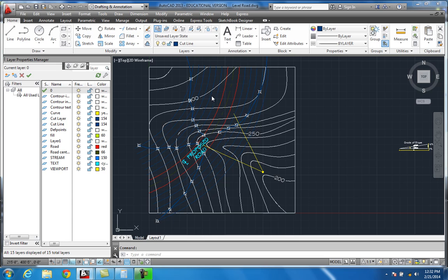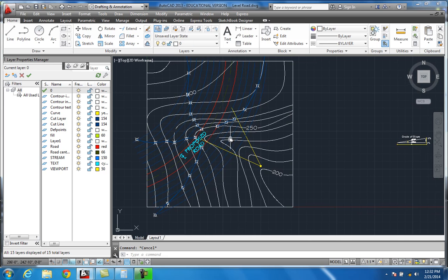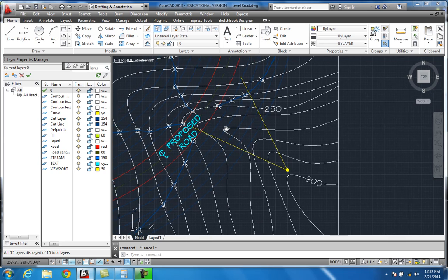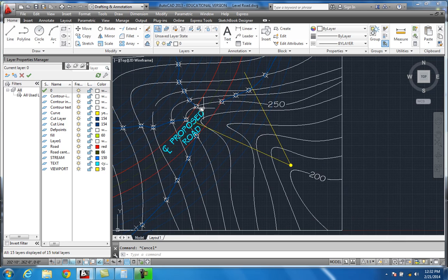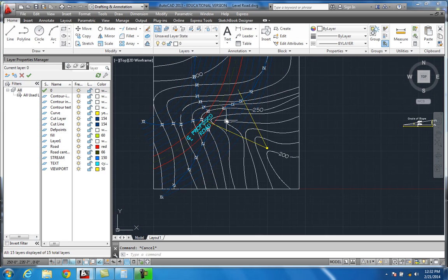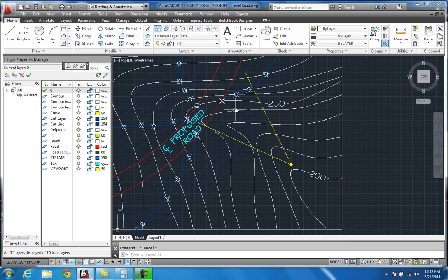Cut line. And basically, at that point, we need to go ahead and put a fill. Now, the fill, there's 250. There'll be a little bit of fill right in here because there's 250. There'll be a little fill right there, but the most of the fill, we can use these same lines because we cut and fill both was a 2-to-1. Now, they can be different. They can be a different angle of repose. They might be 1.5-to-1 or 3-to-1. And the other one would be 2-to-1. You know, they can be opposite or completely different, or they can be the same.